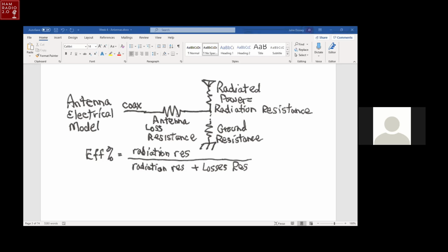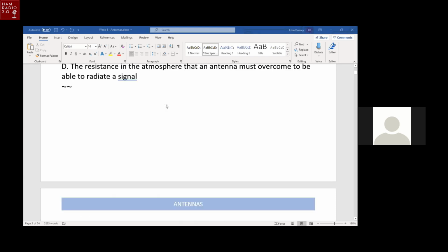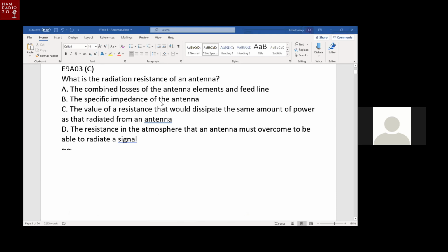They're harder to see for those people that have to hide antennas. Second, that might be all the wire you have. It's okay to use a 22 gauge wire for antennas. They work. They just have a little bit higher loss than if you had used 12 gauge wire. So that's part of the antenna loss. So what is the radiation resistance of an antenna? We'll start with that part of the question.